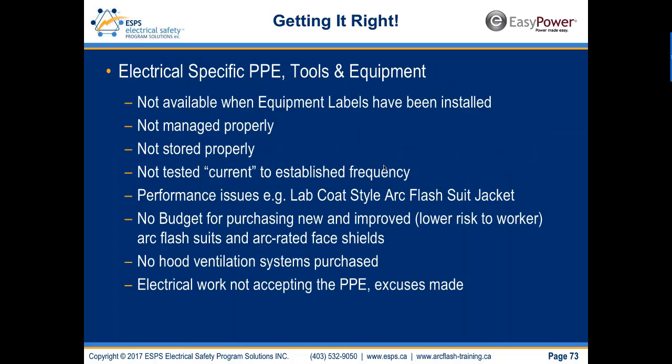The PPE, here's some of the problems I see in industry. It's not available when the equipment labels have been installed. If it is available, it's not managed properly, it's not stored properly, it's not tested current to establish frequencies. There's performance issues with these lab coat style arc flash suit jackets that open when you bend down.